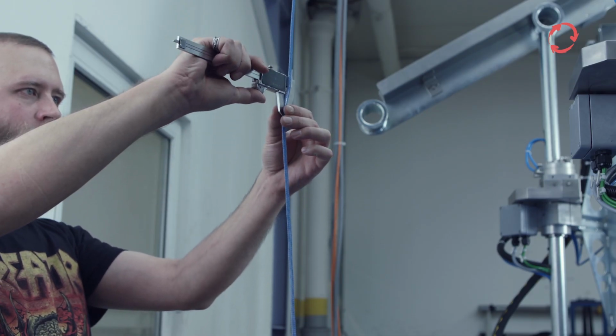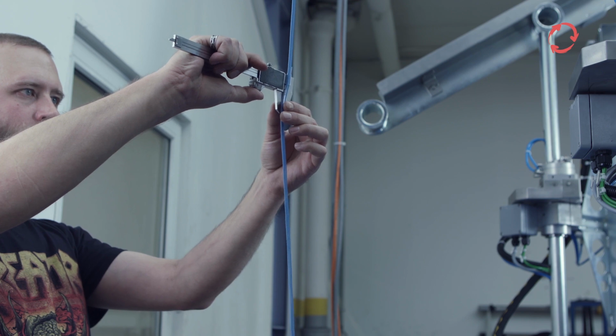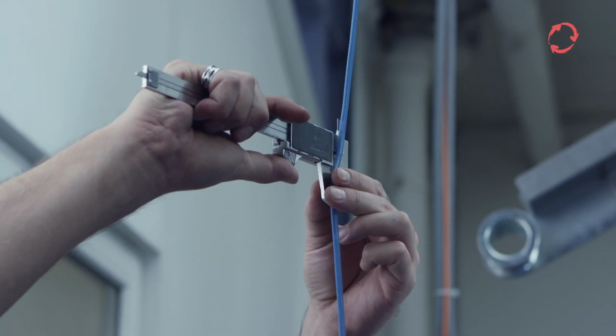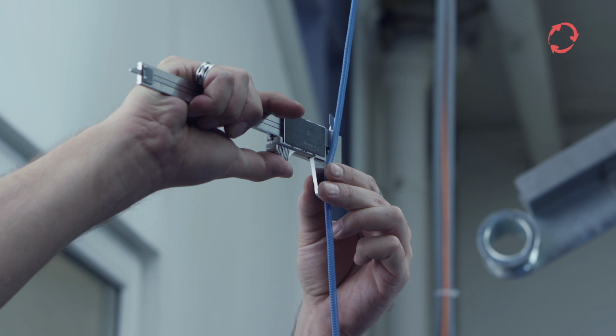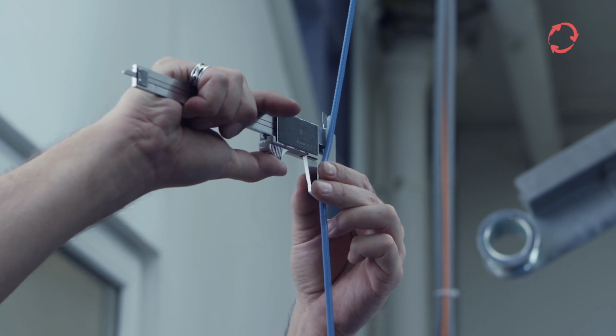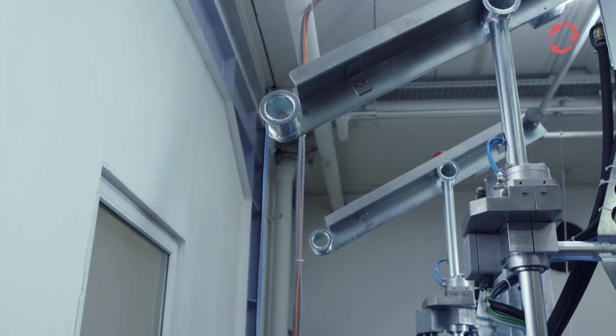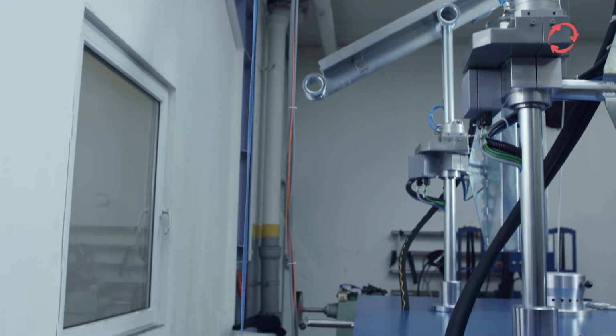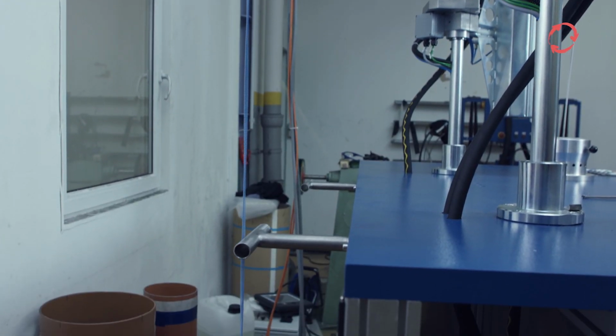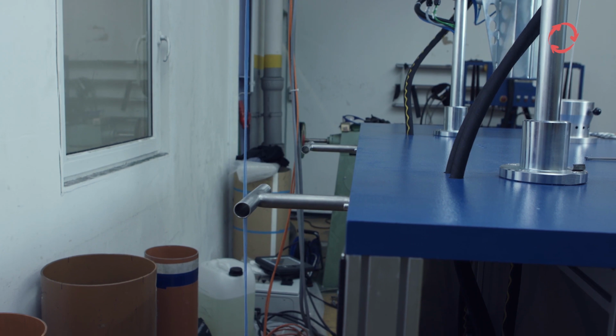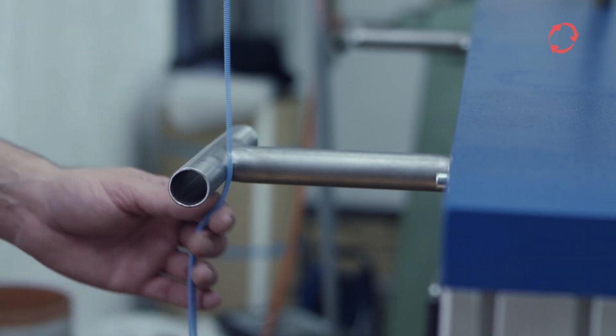The dimensions of the spirals must be regularly checked during the first few minutes of the winding process. If needed, the process parameters must be corrected. The spirals, which are wound until the desired dimensions are reached, are not suitable for sieve production. Once the desired size has been reached, the spirals are guided to the provided cans.